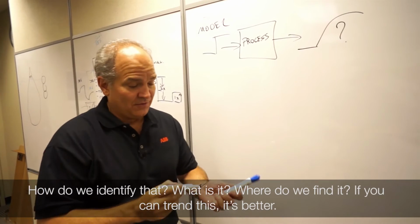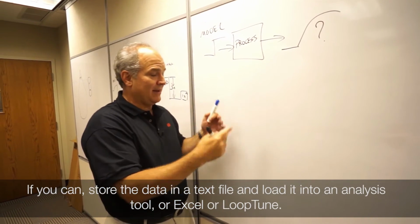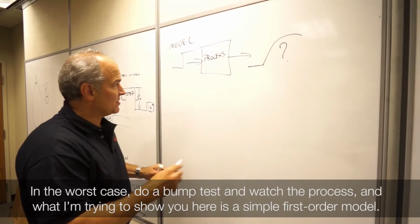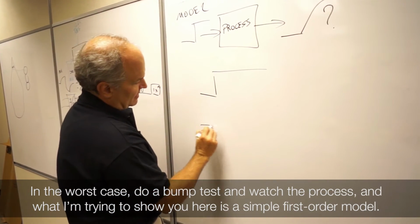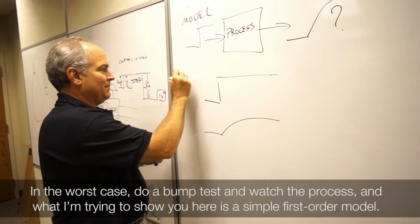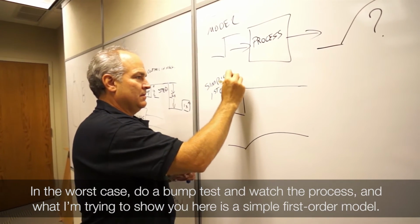Well, if you can trend this, it's better. If you can store the data in a text file and load it into an analysis tool or Excel or our loop tune. But in the worst case, you can do a bump test and then watch the process. What I'm trying to show you here is a simple first order model.